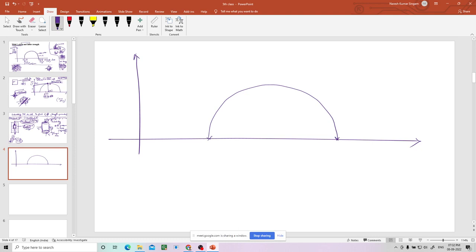So what are these points? These points are referring to the principal planes. This stress is major principal stress, comma tau 0. This is minor principal stress, comma 0, because tau is 0. Here of course sigma 1f, right? And what is this? Sigma 3f, comma 0, right? Because they are principal stresses, tau is also 0. So you can take any plane and you can draw this Mohr circle.